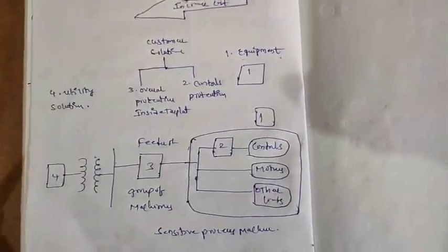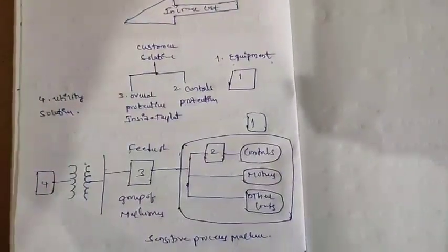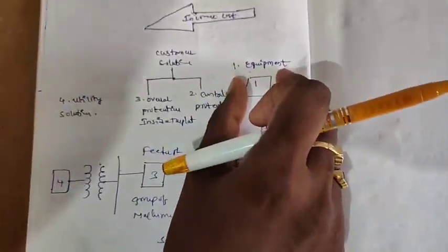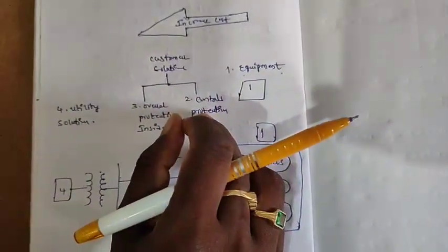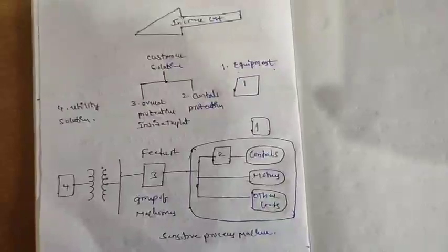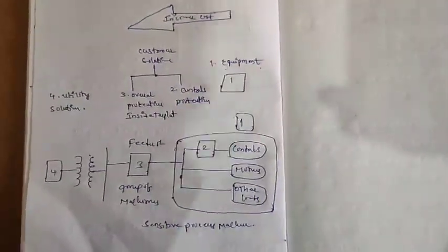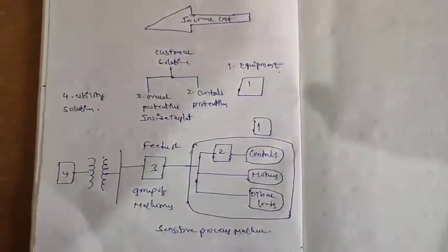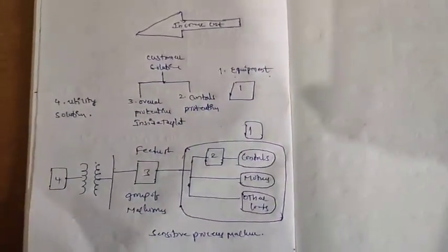If you decide that the equipment can be designed with respect to that voltage sag problem, it can withstand the minimum ride-through capability. We discussed in the earlier class, last class, area of vulnerability, that the sensitive equipment can withstand the minimum voltage, that is the minimum voltage ride-through capability.